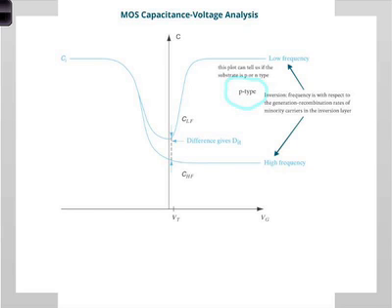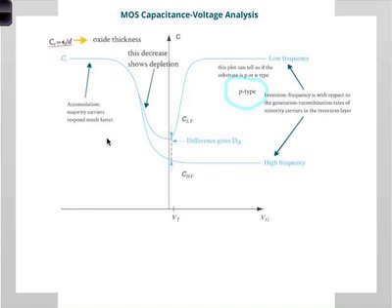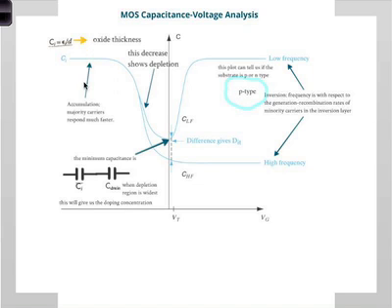And of course, again from this plot, you can tell whether it's p-type or n-type. Here in accumulation, the majority carriers respond really fast, so there is no contribution from them pretty much. Okay, and this decrease shows depletion, as we saw. And the oxide capacitance we saw before is epsilon_i, the permittivity of the oxide, divided by the thickness of the oxide, which will become very important shortly.